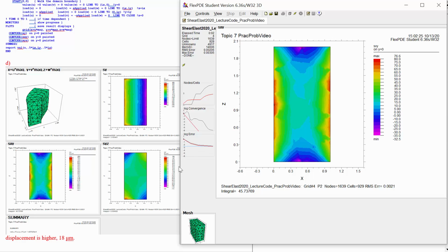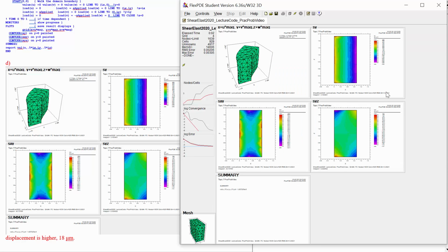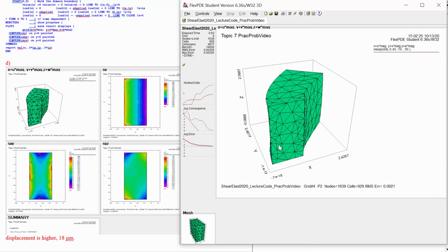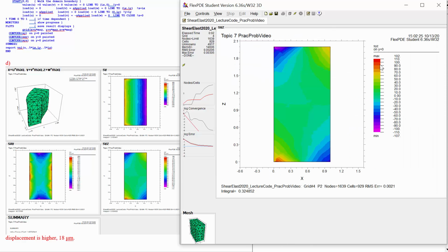Now what about the YZ shear stress? Well, this is not 0. Now that we're not putting those counteracting forces to force the only stress to be this XY shear stress, then all kinds of crazy stuff happens, right? We've got some shear stress on Y surfaces in the Z direction, which back to the original object is like the out of this page in the up direction. So where this is positive down here, we've got one coming out pushing up, and in this corner coming out pushing down to counteract this stuff.